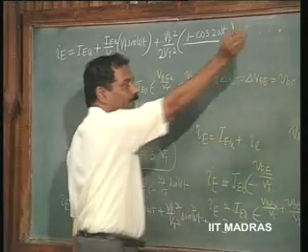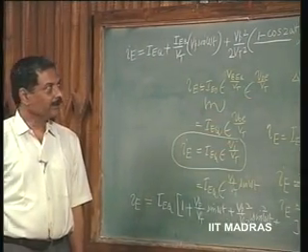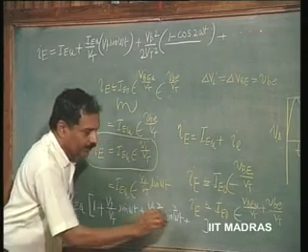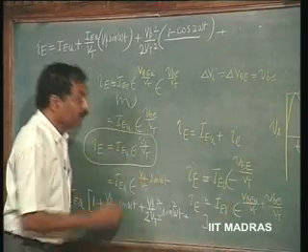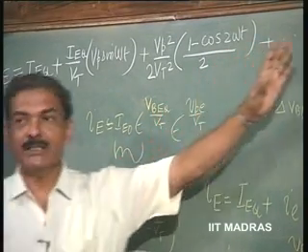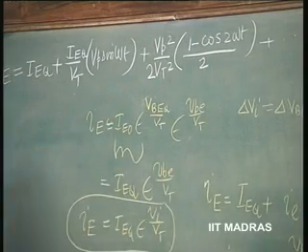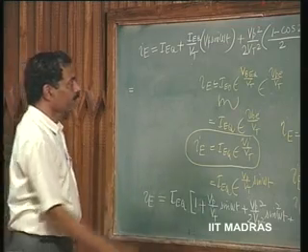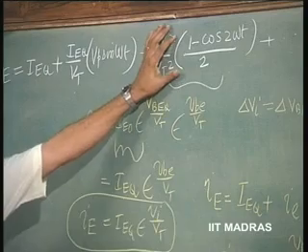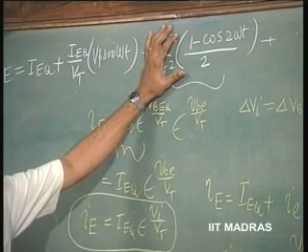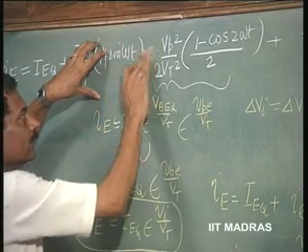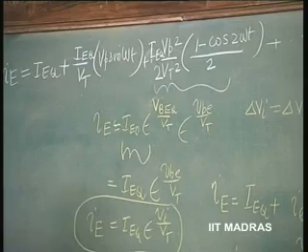So, ignoring the other higher harmonic factors, because there will be x squared by factorial 2, which is 2, and x cubed by factorial 3, which is 6, and so on. So, that will be reducing. So, the harmonics get reduced. So, we have here an important piece of information. If we want this to be very small, this factor Vp squared by 2 Vt squared, a dimensionless quantity, should be very small compared to this, into IEQ, because IEQ has been coming everywhere.